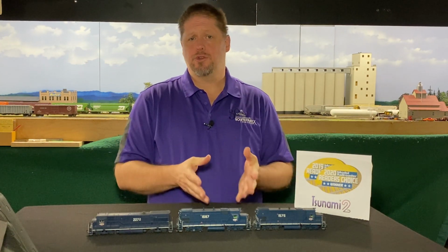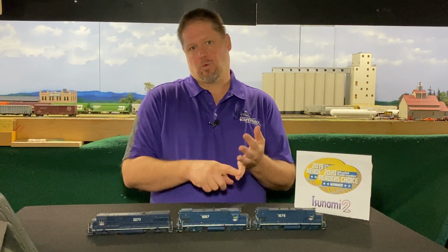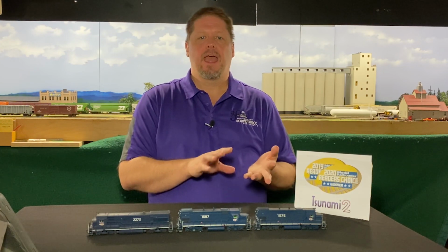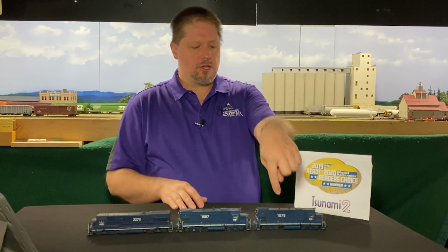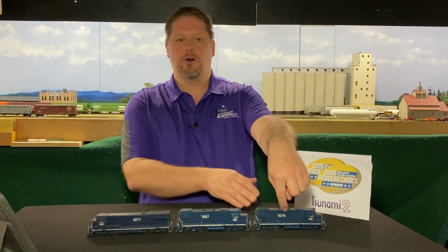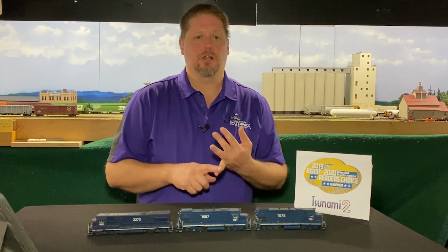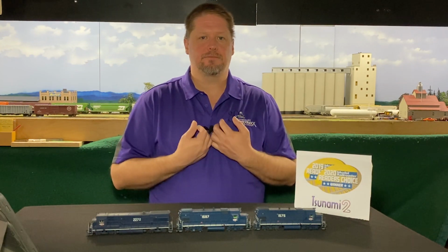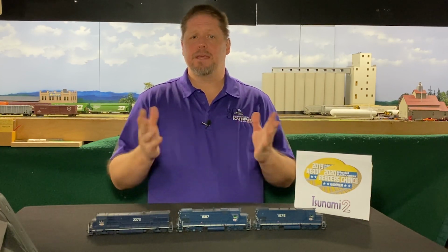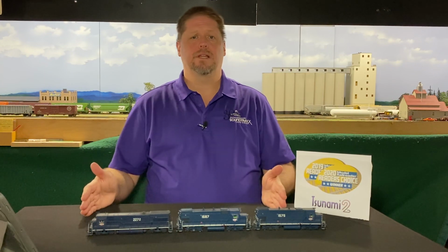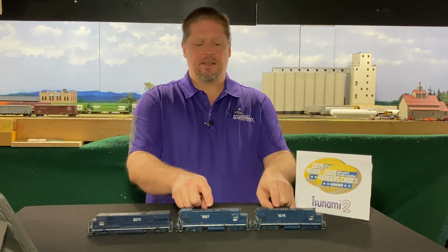CV19 is where the consist address is stored. It's a short 2-digit address, a number between 1 and 127. What that does is it's basically an alias for your consist. You can use the first 2 numbers of your lead locomotive, like 15. You can use a club member ID number, or in my case, I tend to use my sports jersey number, number 20. It can be any one of those numbers, again, 1 to 127. You set that into CV19.